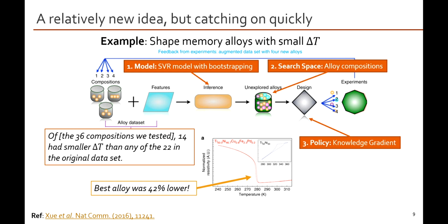What they did is they used experimental design techniques to optimize the composition of shape memory alloys such that this property called the hysteresis is minimal. Now, this hysteresis defines how different the temperatures are when I cool down a material and it will reform into its original shape, or when I heat it up and I can train it into a new geometry. And if you simplify and get these close together, I believe that gives you good properties for energy damping applications.